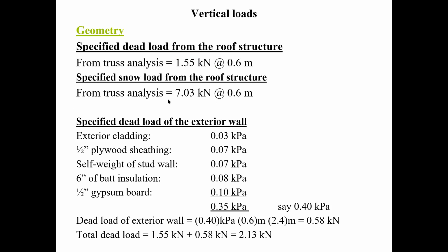As a matter of fact, when I looked at this here, I did a quick calculation and I think I ended up getting 7.025 something, which rounded up to 7.03. So I know that ADA did not make a mistake, and I did not make a mistake when I inputted into the ADA. There's my snow load, and there's my dead loads.